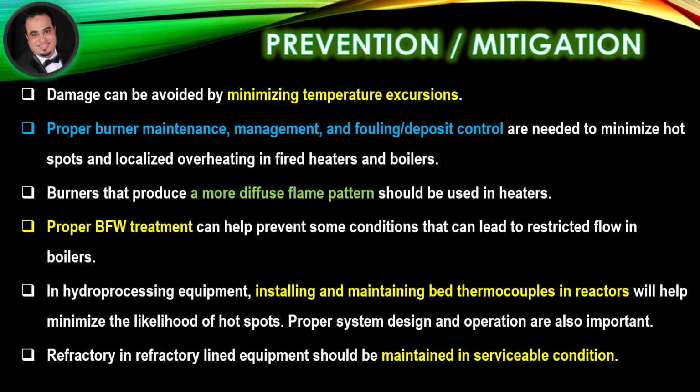In hydroprocessing equipment, installing and maintaining bed thermocouples in reactors will help minimize the likelihood of hot spots. Proper system design and operation are also important. Refractory and refractory lined equipment should be maintained in serviceable condition.